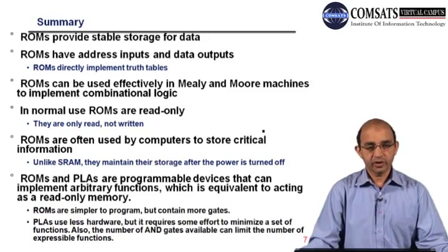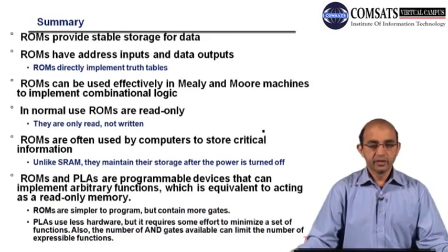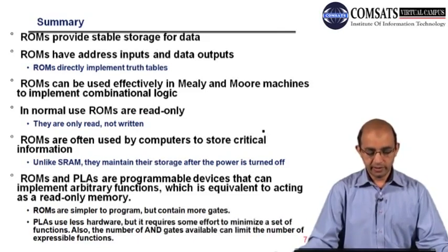If we have a ROM that includes a decoder and the other circuitry, we have to generate all the minterms, even though we are not using all of them. To avoid that, we replaced the decoder with a new configuration that can be programmed. That's why we call it a programmable logic array. So that's the summary for the ROM.